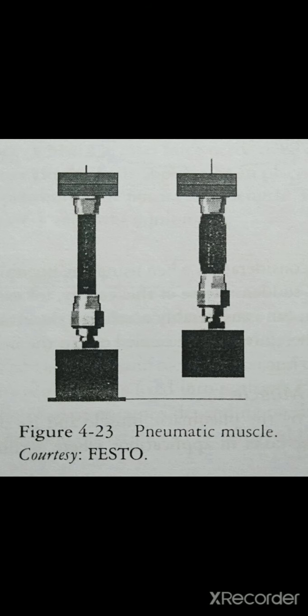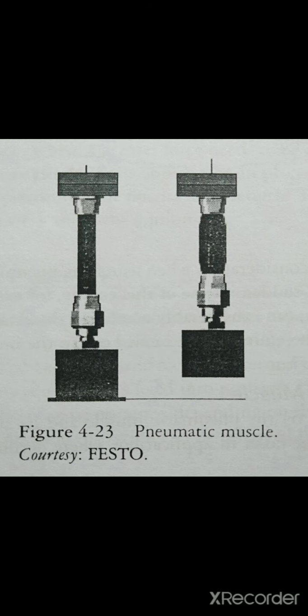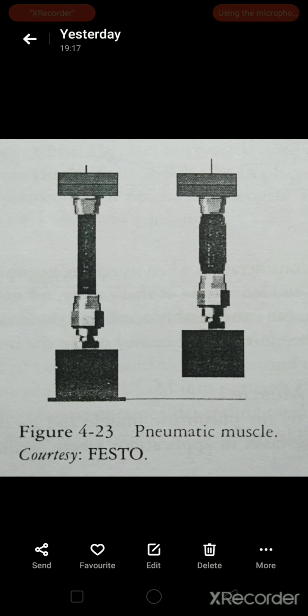There are certain disadvantages also that you should know. Double acting function is not possible. Guidance of load is not possible. Etching of the rubber material is the biggest challenge with a pneumatic muscle, along with the problem of overloading.